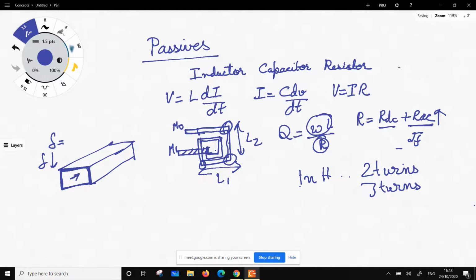So I can make an inductor using more turns in a smaller space, but then the Q of the inductor is going down, right? So if I was to do a high Q, usually I don't exceed more than 2 turns on a chip. Just make a 2-turn inductor, make it as large as it takes to be, and that way you will have a higher Q on the inductor. I don't go beyond 2 turns, while the process will allow you to do any number of turns.